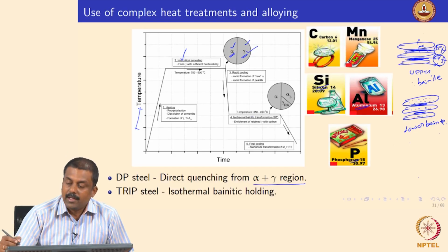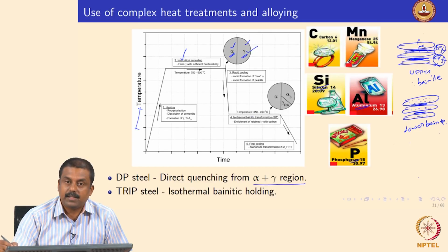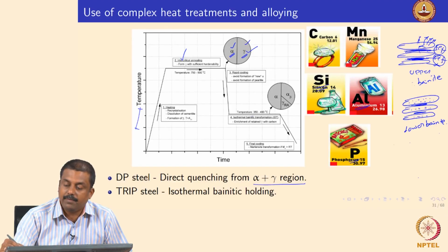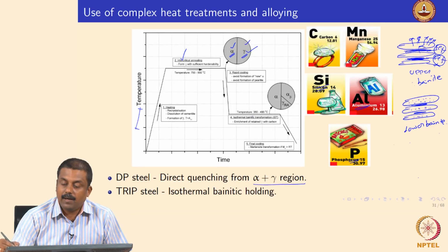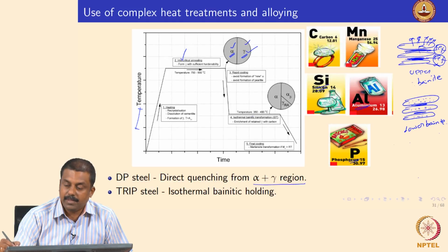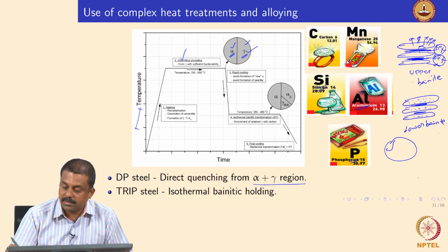Okay. So, if the cementite is suppressed during the formation of bainite, when austenite is transforming to bainite, first ferrite is nucleating, right. Ferrite forms and then the carbon atoms try to go out of the ferrite, but because of the extremely low solubility of silicon and aluminum in cementite, what do I mean by solubility? The cementite lattice cannot keep the silicon and aluminum atoms. Suppose you have the austenitic, two-phase microstructure from the intercritical region. For example, this is an austenite grain. If you make it bigger, imagine this is your austenite grain,